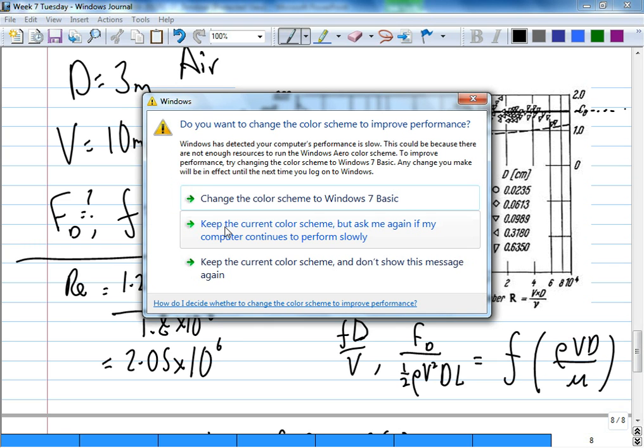Okay, I zoom out a little bit. Oh, the brightness. Zoom out a bit. So 2 million is about here. And go up. Drag coefficient around 0.5 to 0.6. 0.6 or 0.7 like that. Let's take 0.6. Depends on your skill of reading the graph. So, we take that back here.